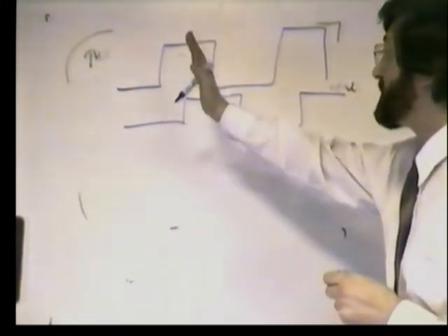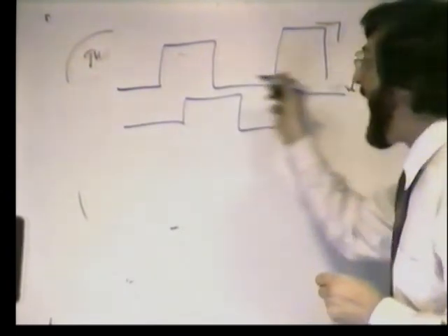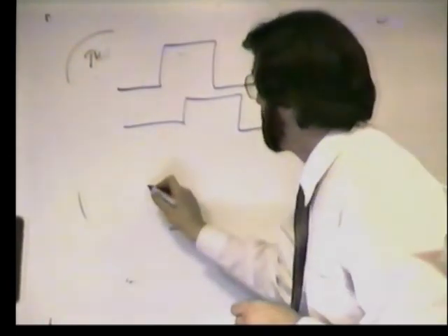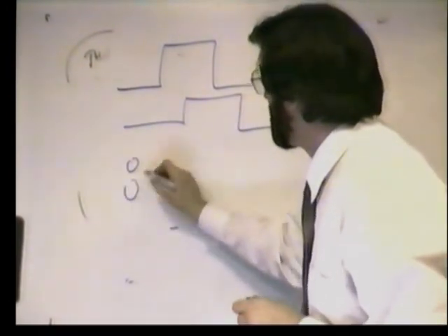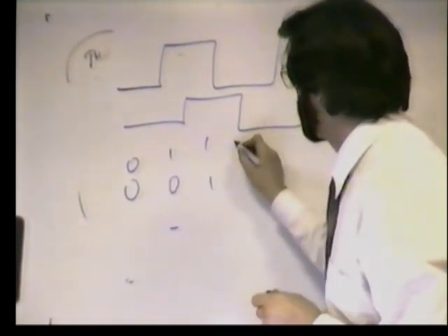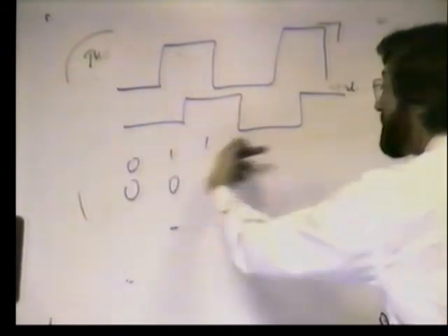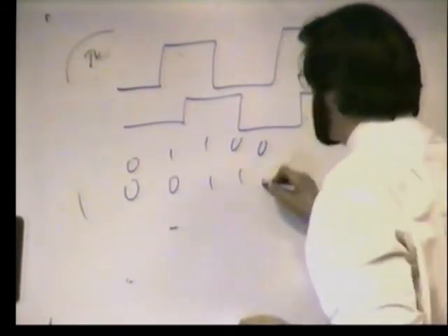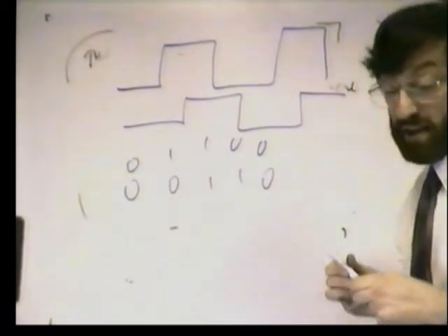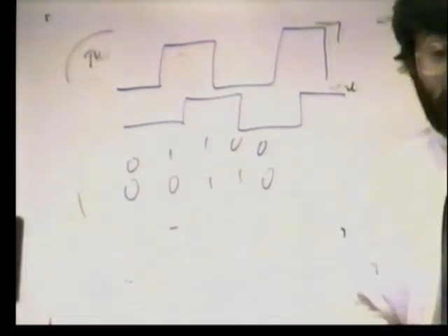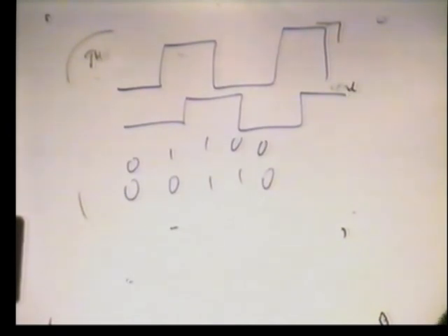This gives us both an absolute quantity and a direction, because the binary pattern can change in one direction only, and you know the direction you're moving through the pattern, and so you know whether you're moving forward or backwards using quadrature encoding. So that ends this session on data acquisition.